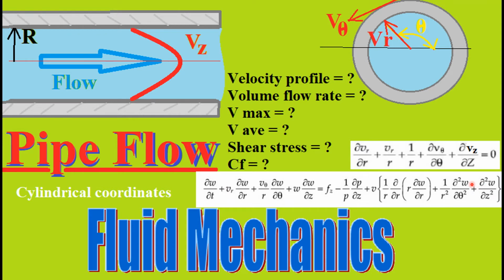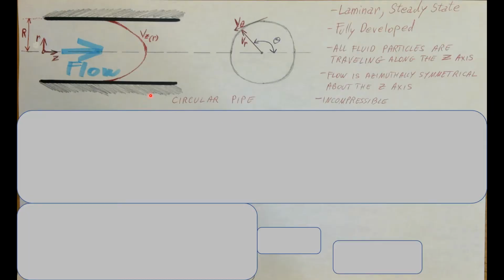Here's the Navier-Stokes in cylindrical coordinates and the continuity equation also in cylindrical coordinates. Here's a big list of things that we're going to take a look at and try to figure out. Okay, let's get started. In order to find the first thing they asked us, which is the velocity profile, we're going to have to rely on Navier-Stokes, otherwise known as conservation of momentum. We're also going to use conservation of mass to help us cross some things out from this large Navier-Stokes equation.